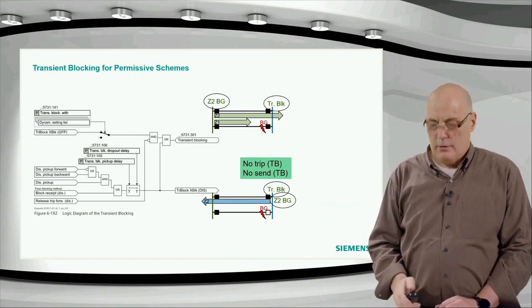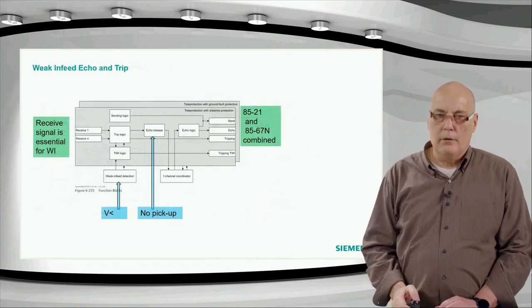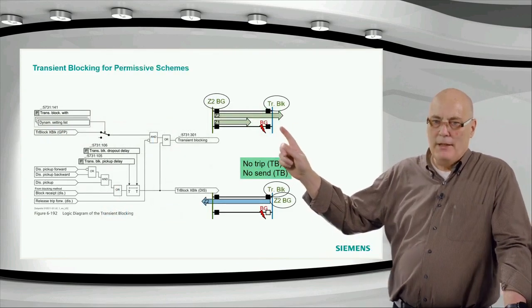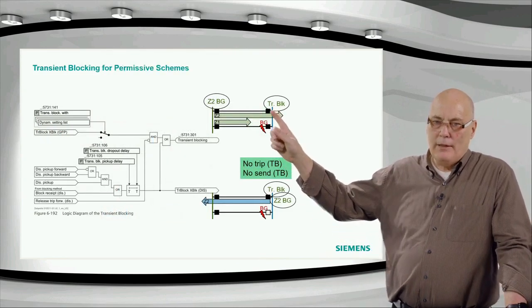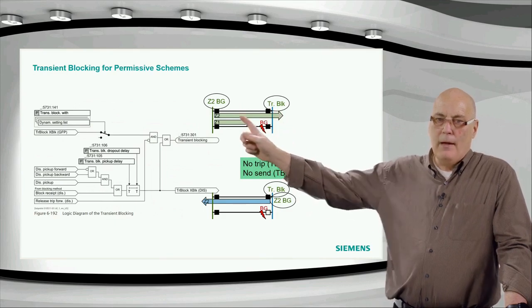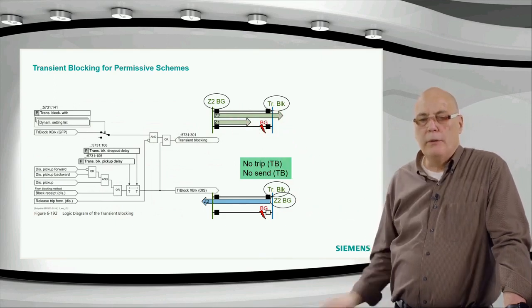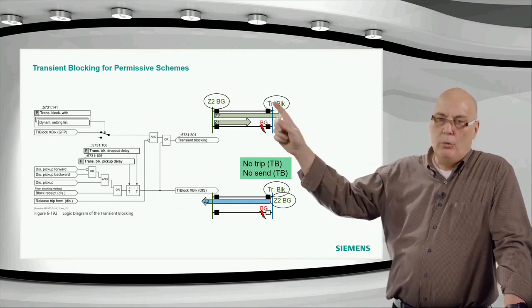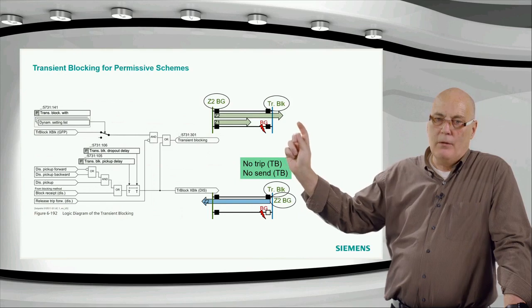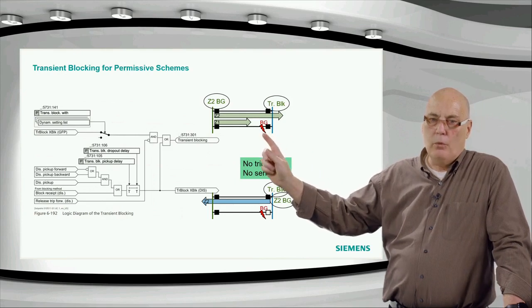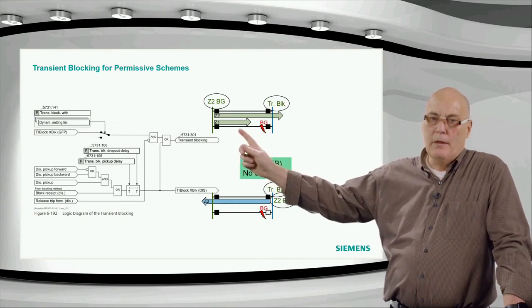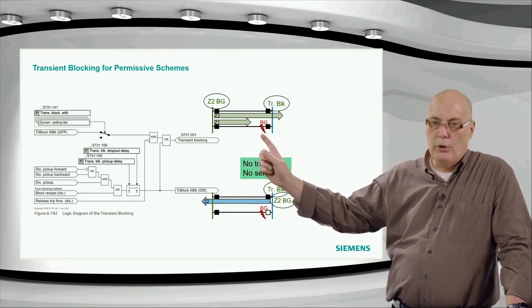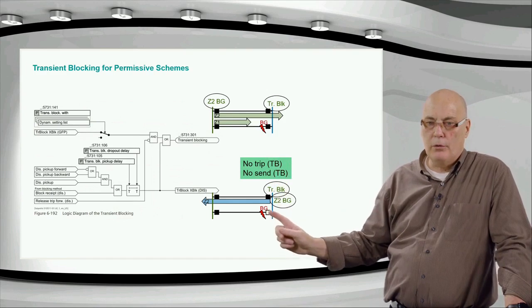Then I think there are some diagrams. No, they won't. I have to go through it one by one. Sorry. So what happens here initially, we will have a pickup on the right-hand side reverse. And on the other side, we'll have the zone 2B ground. So the left-hand side at the top will be sending a signal. Here we will be receiving the signal, right? And this side at the bottom, we'll see the fault here outside zone 1, but inside zone 1. So maybe the teleprotection is not working so quickly. And then we go over to this condition trip.